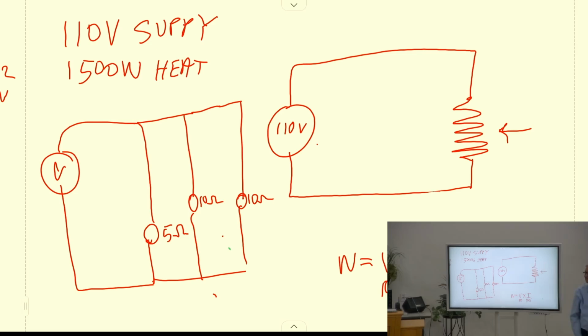But that's what they're saying: in areas where they have bad storms, people would backfeed the system with their generators and kill linemen. The lineman would go up there to fix the pole, because you backfed it with 120 volts. Well, you just stepped it up. You have to make sure they shut off the generator. People used to make a suicide plug, they call them, to an outlet, and you power your house through an outlet.